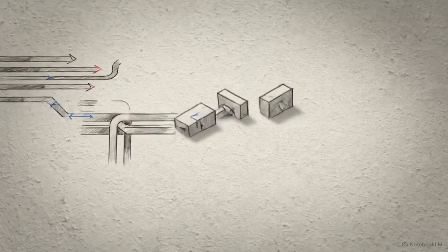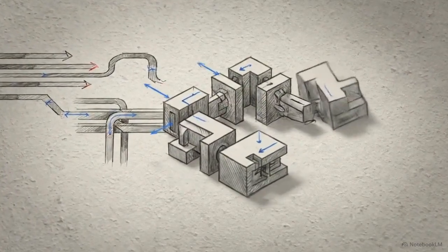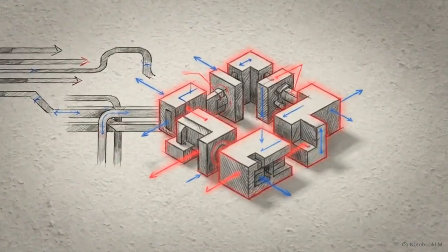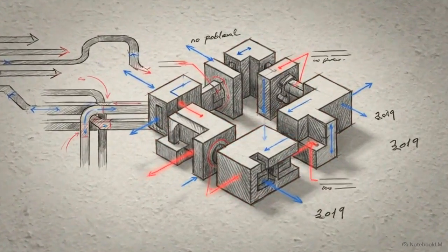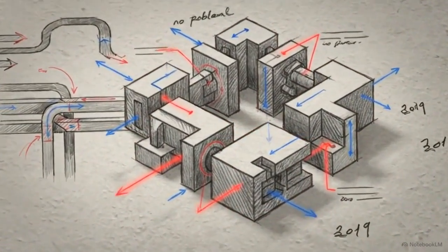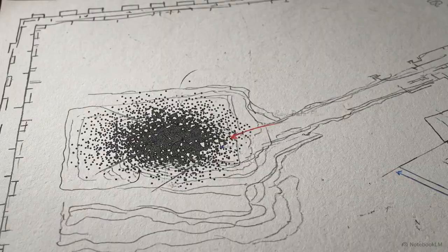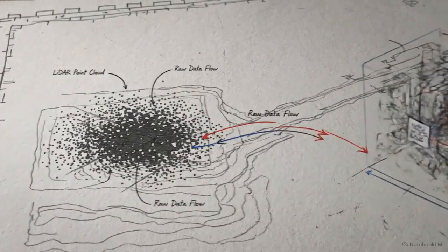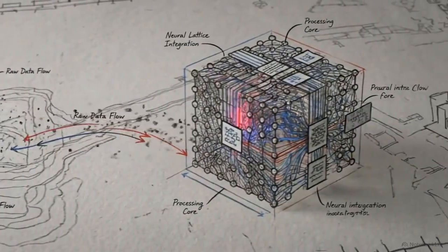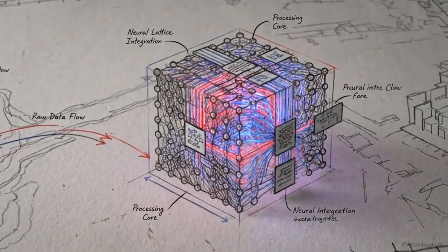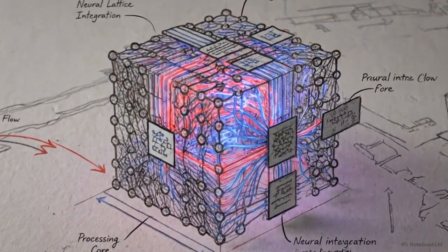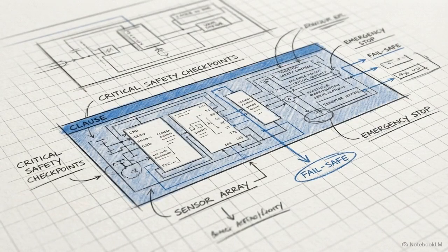Traditional functional safety, governed by ISO 26262, manages random hardware faults and deterministic software errors. Here, safety is guaranteed through verifying precise, rigid logic gates. Machine learning removes explicit code. When a 3D LiDAR point cloud flows into a neural network, behavior is determined entirely by the training data. This shift creates a critical gap covered by the ISO 21448 standard, known as SOTIF.